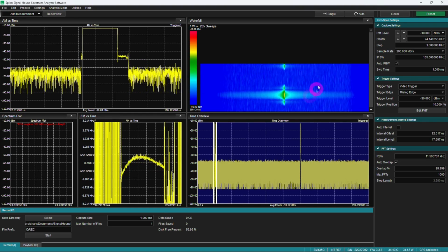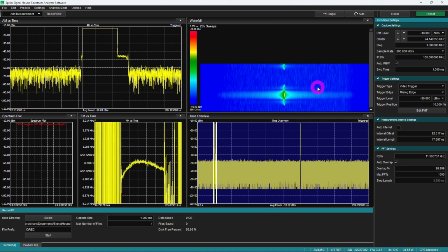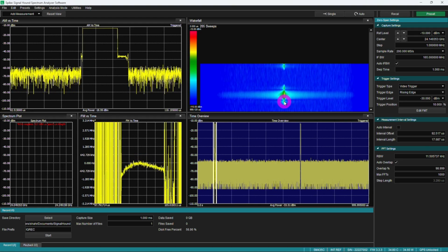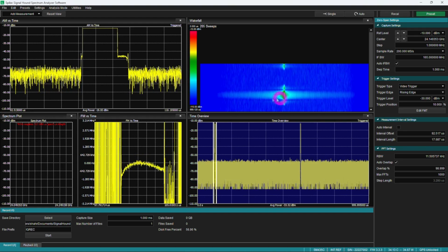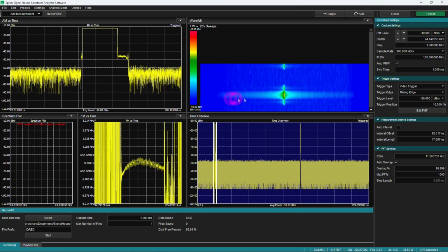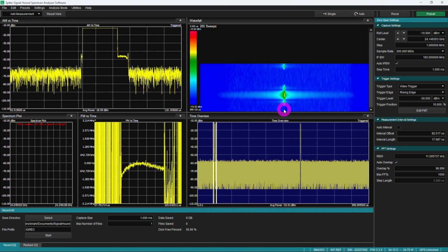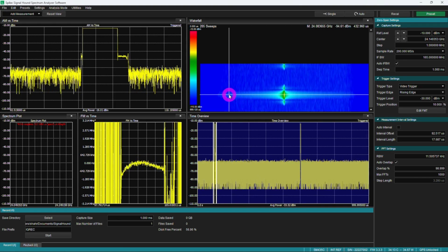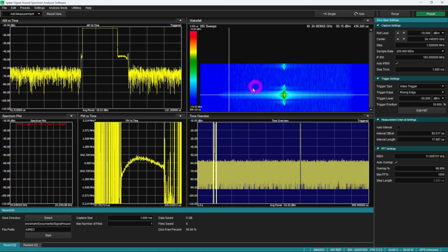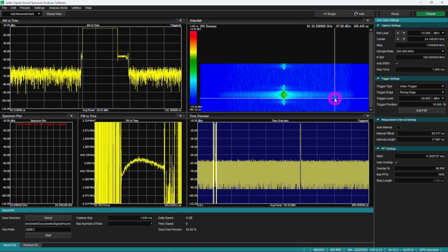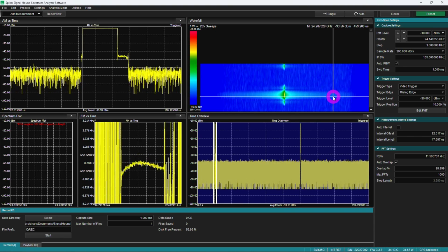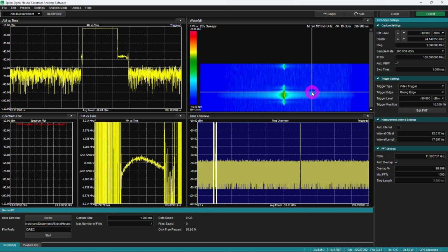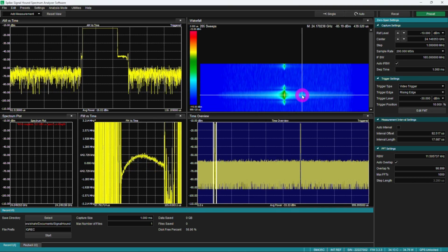The first thing to note is that if I look at the waterfall, we can see multiple unique features right away. We see an area where the signal begins to be present, then there is a little bit of quiet time, and then there's a big frequency spread here, and we can find out how much that is, and then there is another period right after it. Now I can move a marker on this very easily, and from this point, we're at 24.083 gigahertz. You can see that at the top right, and move it all the way to the other side, 24.208. So it's not a very big frequency span, but it is some pulse spreading. And that's important for a radar because you want to make sure you're still within the window. So we want to analyze that a little bit further.